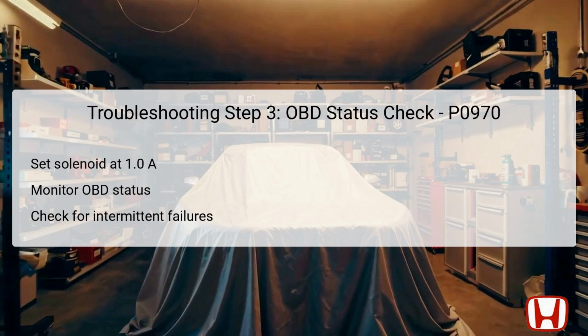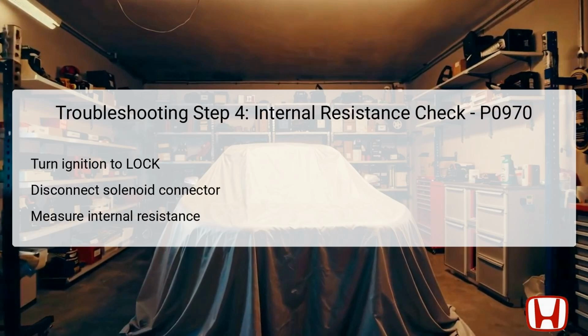Another response, not completed, indicates the need for retesting under the same test conditions. For step 4, begin by turning the ignition switch to the lock position to ensure the vehicle's electrical system is off. Next, proceed to disconnect the AT clutch pressure control solenoid valve C2P connector, which is crucial for safe measurements.